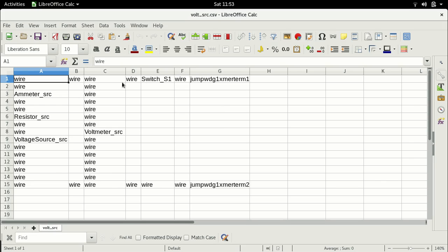When the switch is turned on, a current is flowing. This current is increasing. When the switch is turned off, that current drops to zero. So there is a direct drop to zero. So the rate of change of current is very large, which means that the EMF induced in this transformer is also going to be very large. And that is what is causing this instability. This transformer has energy and doesn't know what to do with it, right?